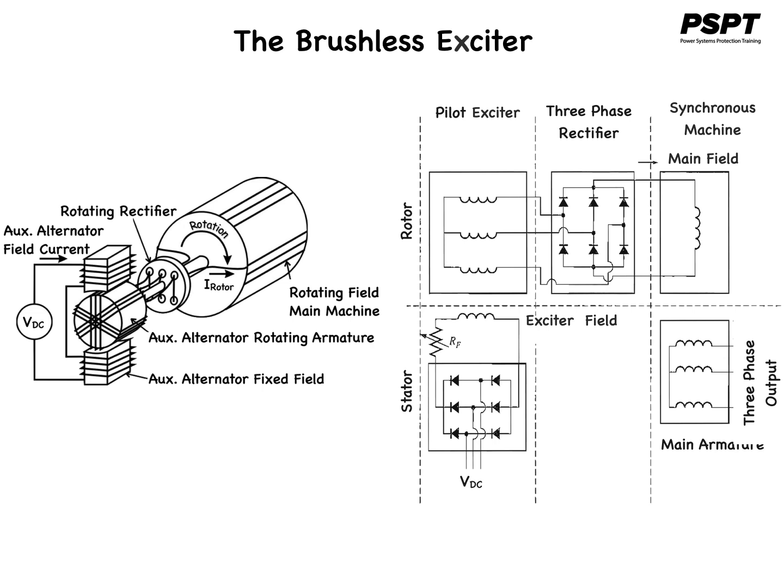On larger generators and motors, brushless exciters are used to supply the DC field current to the machine. A brushless exciter is a small AC generator with its field circuit mounted on the stator and its armature circuit mounted on the rotor shaft. The three-phase output of the exciter generator is rectified to direct current by a three-phase rectifier mounted on the shaft of the generator, and it is then fed to the main DC field circuit.